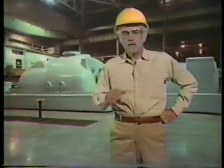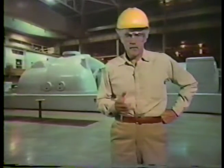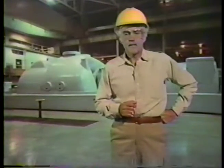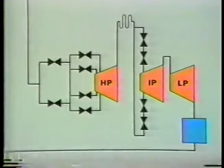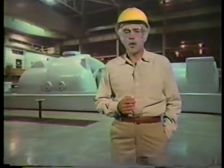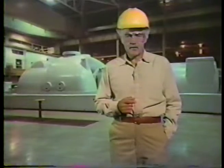As we said, the main stop valves admit steam to the HP turbine during normal operation, but shut it off during shutdowns or emergencies. Shutting off the flow of steam is called a turbine trip. The term turbine trip can apply to any situation when the valves of the turbine are closed and the turbine is out of service. But during the course of this unit, we'll use it to refer only to shutdowns that are unplanned and occur under emergency conditions.